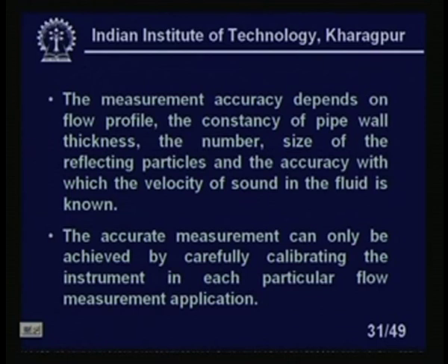The accurate measurement can only be achieved by carefully calibrating the instrument in each particular flow measurement application, right. So, like electromagnetic flow meters, you have to calibrate individually in all cases, okay. That restricts the use of these instruments a lot, but it is quite popular for some other applications because it is a totally non-invasive technique.